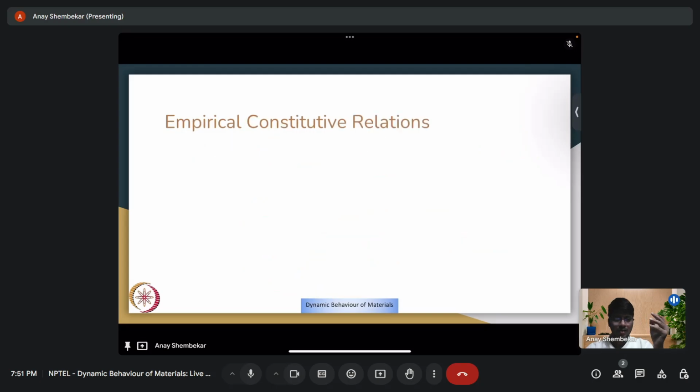So to understand materials, because we are interested in studying their dynamic deformation, an important point along the way comes in the form of constitutive relations. These are important so that we can use empirical knowledge, package it into a constitutive relation form, and then use that analytical expression to relate deformation of the material with the resistive load that the material will apply, the load that the material will try to resist that deformation.